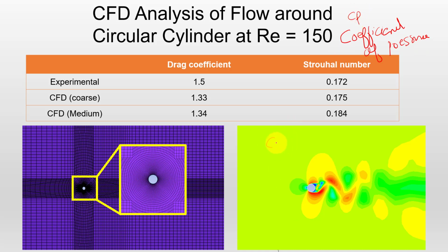And for these types of cases, if you go for turbines, like low pressure turbines, the Cp is defined with the help of total pressure. But for most aerodynamic applications, like external aerodynamics, the Cp is defined by the static pressure. So this is P minus P infinity, the free stream pressure at the inlet of the domain. Like U infinity, we have P infinity as well, divided by 1/2 rho